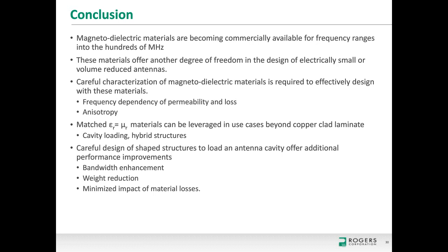The trade-off would be in the lower frequency range, particularly kilohertz, you may be able to find other materials that maybe have a higher permeability. Or another way of saying that is if I were to design a material to work into the kilohertz range, I would start with a different magnetic ceramic that has a lower cutoff frequency and then would allow me to work to have a higher permeability.